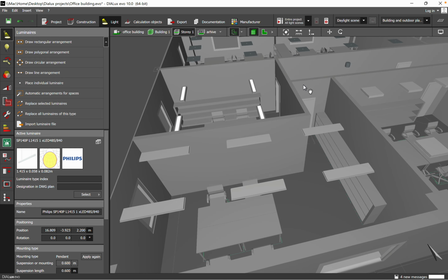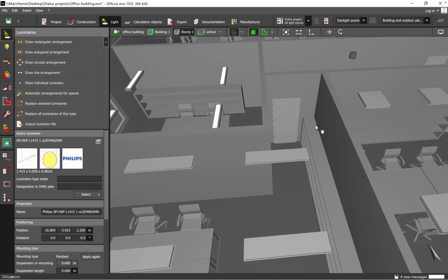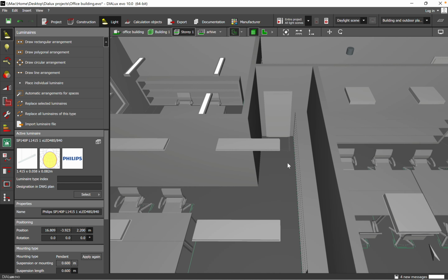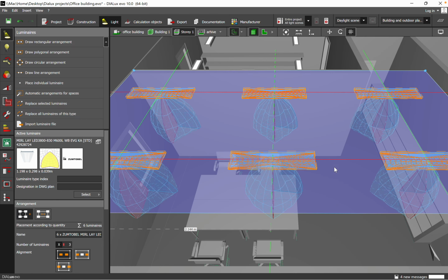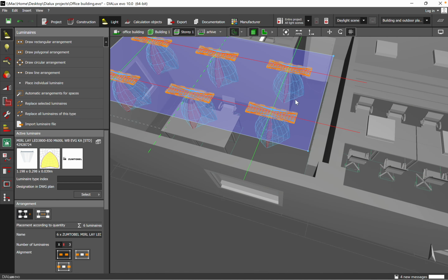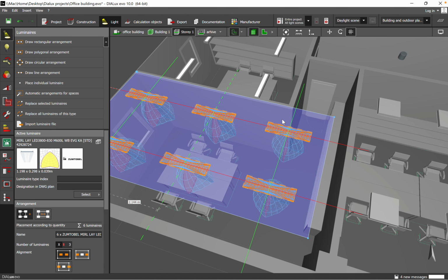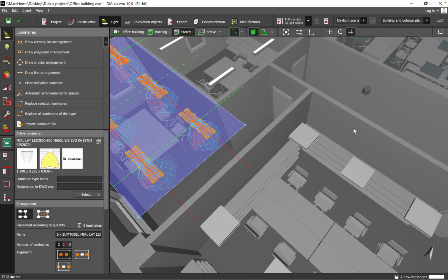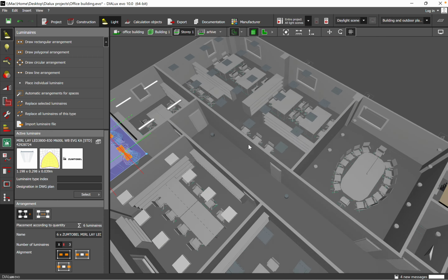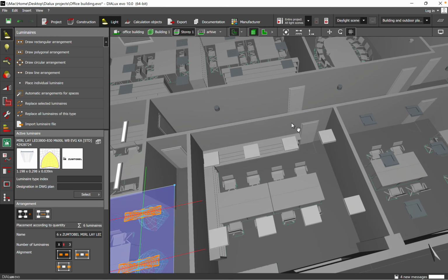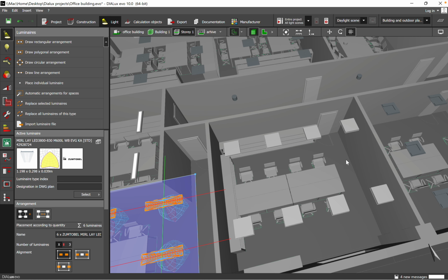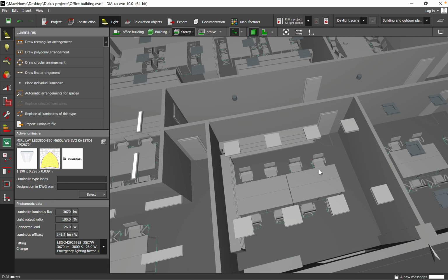Of course, for direct lighting, you can also use a different size, 3 by 12, classical 3 by 12. So not only 6 by 6, but also 3 by 12. And usually in office applications, you have recessed, surface mounted, or suspended mounted. So that's about direct lighting, the most usual solution that you will find in an office building. And then we'll move on to indirect lighting.